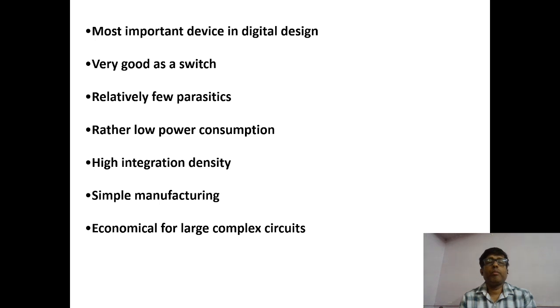Okay, obviously a few parasitic charges can occur, but nowadays there are good fabrication processes and some very good modeling. We can eliminate these types of parasitic charges, which will be created in the metal silicon interlayer, that is, the oxide semiconductor interlayer at that position. Some trap charges will also occur in the silicon oxide.